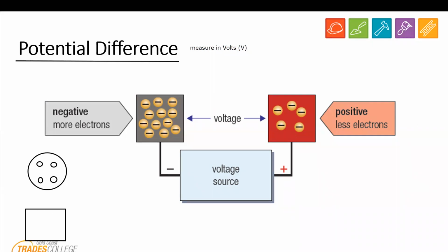Now your switch there is going to have your common there, and just for now, I'm just going to draw the other one, which is number 1. That would be a C. That would be number 1. And then at the top, we'd have our loop. And then these two are unmarked, and this is where our active would go, and neutral. Remember, these terms are for AC. And then we'd have our earth up there. I'm not going to worry about the earth for now. I don't want to overcomplicate this.